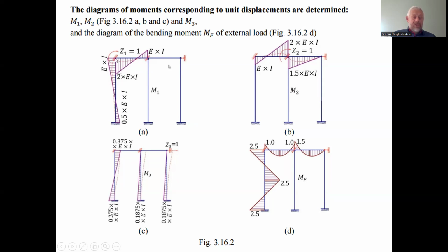We assume only rotation of this one support reaction for the moment m1, and not the linear, straight motion of this supporting rod, and not rotation of the second sliding embedding, etc. Just only rotation of this one. And we have the distribution taken from the directory for the standard beam embedded on the left hand. We can rotate this beam to a horizontal location, making it easy to understand the correlation with the directory's standard options for beams.